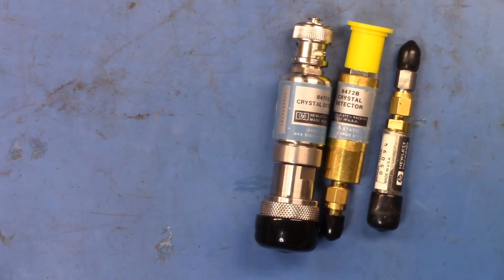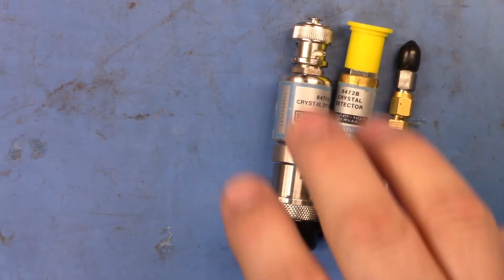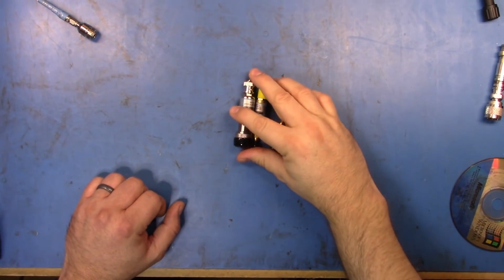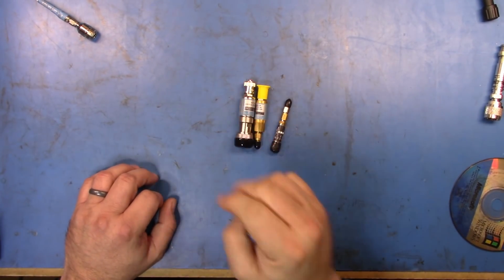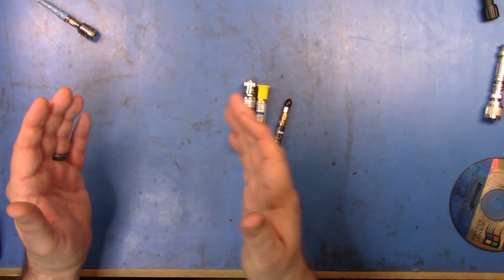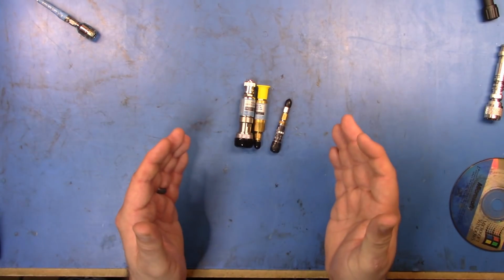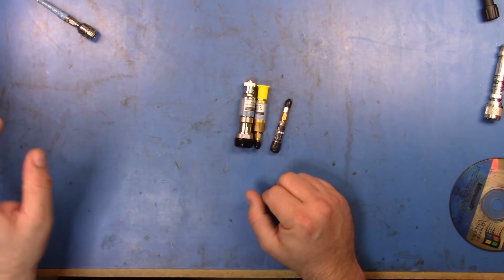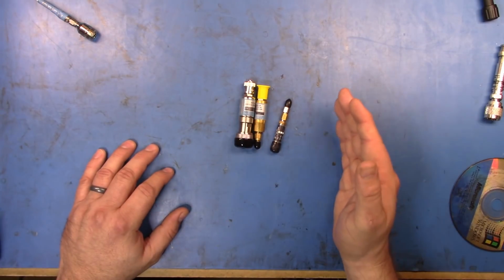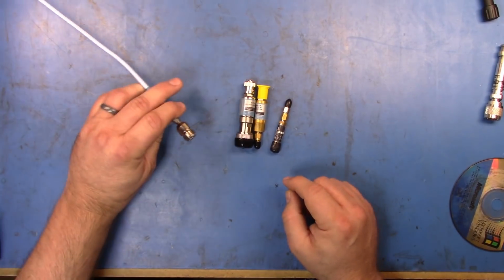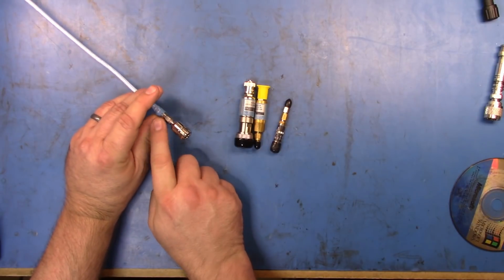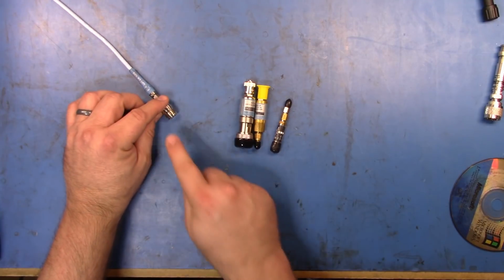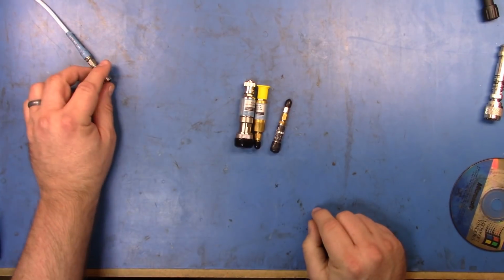To do that, I'm going to need to use three pieces of gear actually. So let's zoom out a bit so you can see these things in a row. The 3 pieces of gear are going to be a signal generator that's capable of delivering minus 20 dBm, and we'll pick a middle frequency of 10 gigahertz. I'm going to use a power meter that enables me to check the power at the measuring point, which will be here where I have my cable connected to the N-type connector, and I want to set this to be minus 20 dBm.